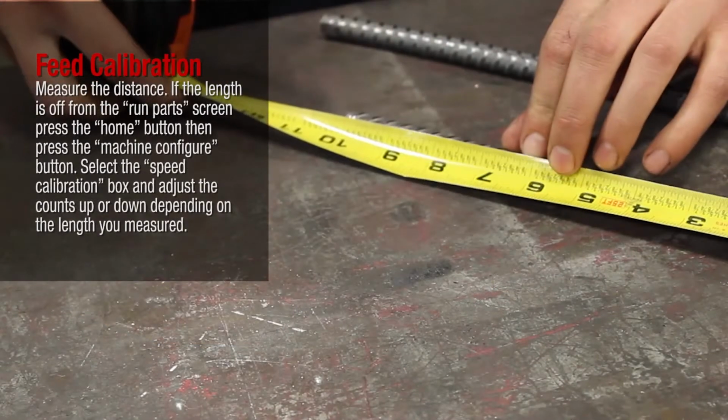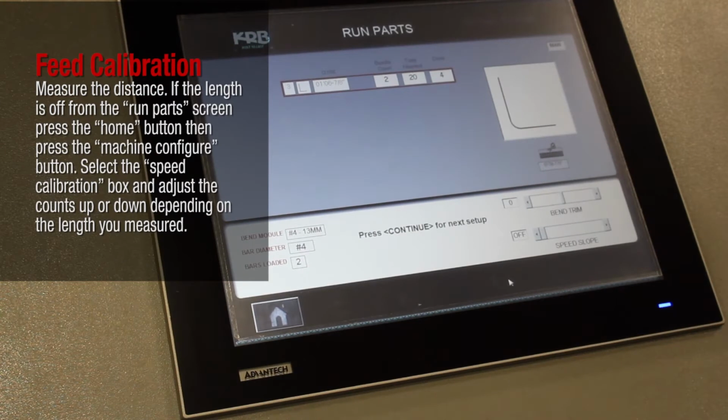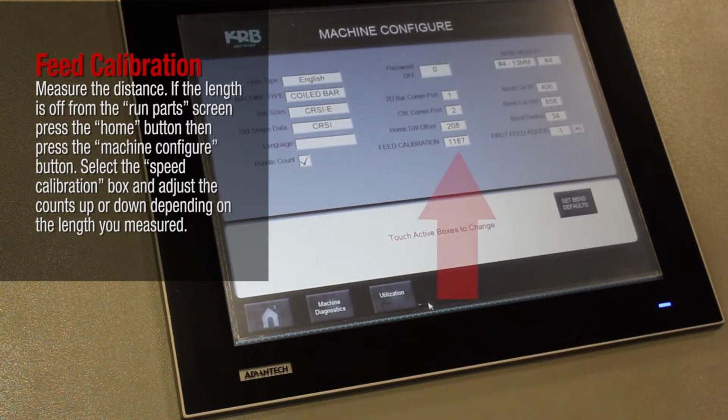Measure the distance. If the length is off, from the Run Parts screen, press the Home button. Then press the Machine Configure button. Select Feed Calibration and adjust the counts up or down depending on the length you measured.